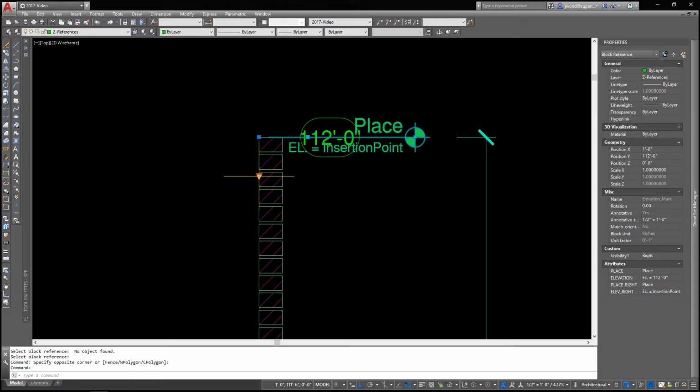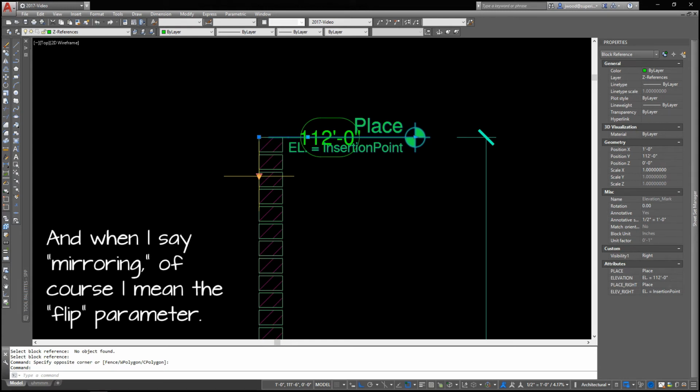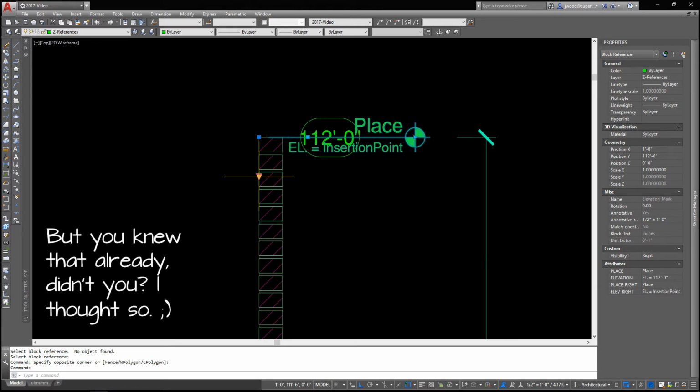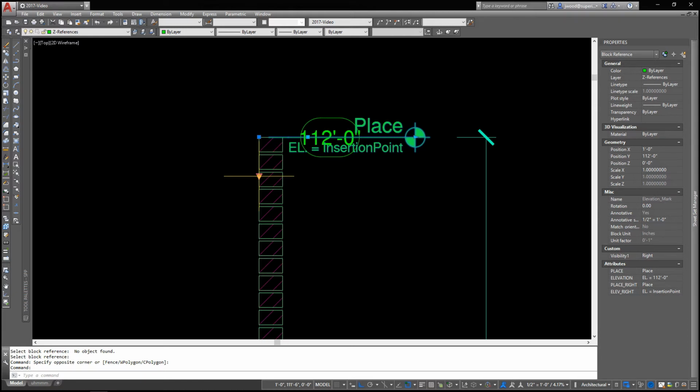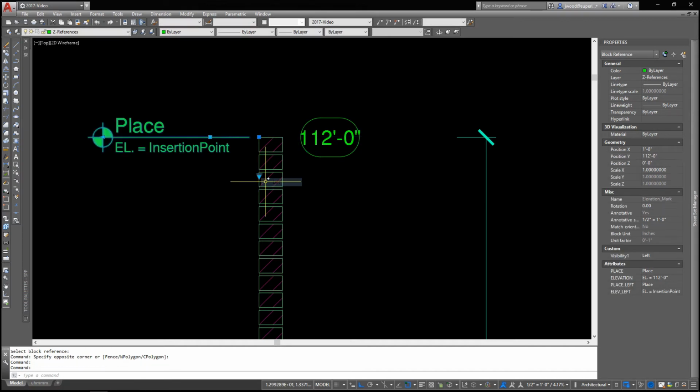And unfortunately, one thing that you cannot do when you are mirroring various parts of a dynamic block is to change the insertion point of your attributes. If they are inserted in the lower left and you mirror them, they're going to have the point where they are inserted into the lower left mirrored. So in order to get that kind of thing to work, I have to have two sets of attributes for everything that displays the left-hand version and the right-hand version.